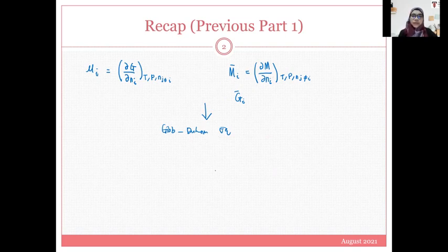From the previous study, we also covered the introduction of the fugacity. Fugacity is the replacement for the limitation of the chemical potential. For example, in the system, the chemical potential for the species will be the same, but the fugacity will adjust the pressure to obtain the value. We can obtain values of fugacity that are different for each species or for each phase.